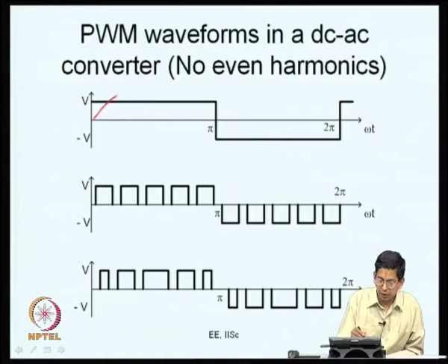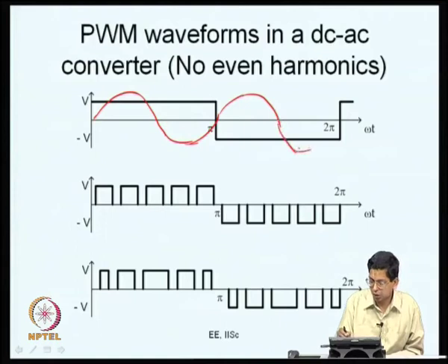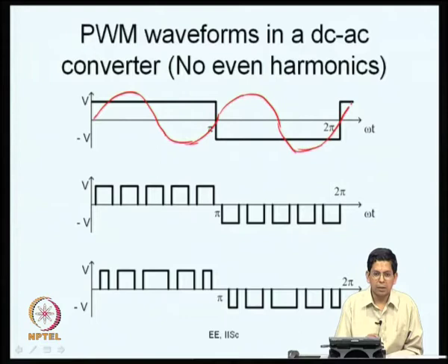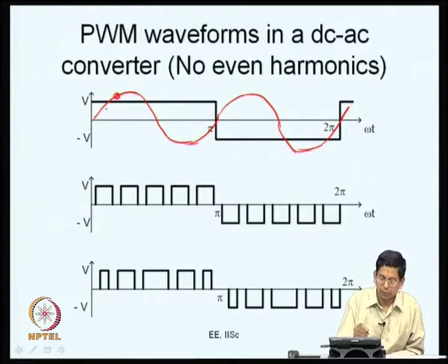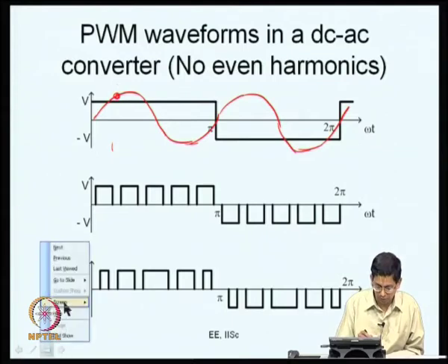Assuming, let us say you want to check whether it has a second harmonic. What you do? You multiply it by a second harmonic as shown here now. Right? Now, take some arbitrary instant, say here, and the same instant 180 degrees later. On the same instant, let me just change the color of ink.